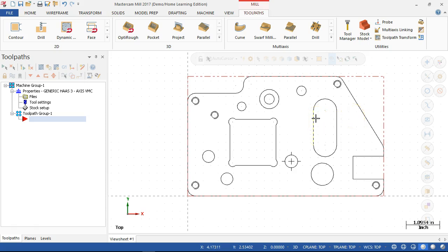And if not, then we're going to have a piece of 3/4 inch material, cut around, do all the geometry, and then flip it over and machine off the backside. All right, so again, that process is, what is our stock selection? What are we looking at in the way of material removal? And what are the capabilities of the machine?